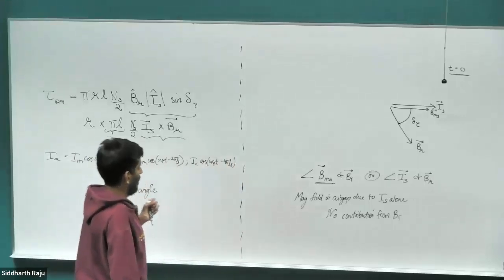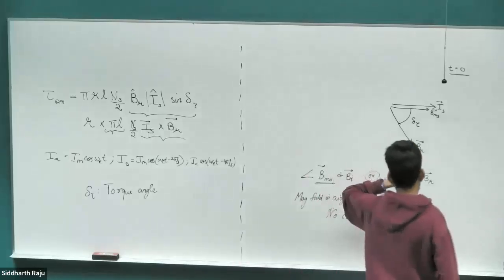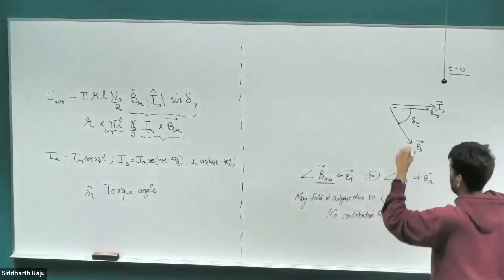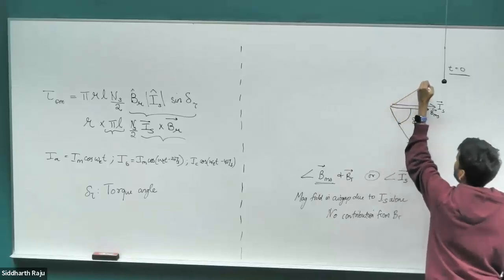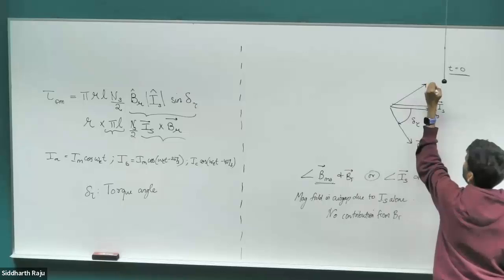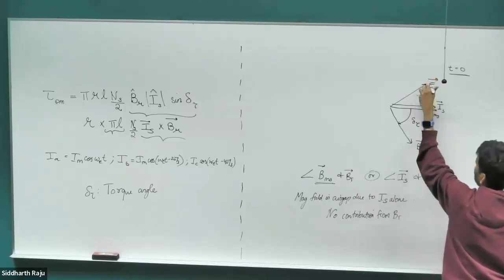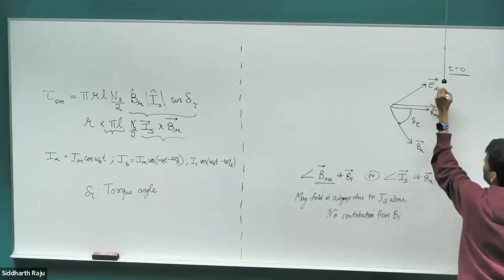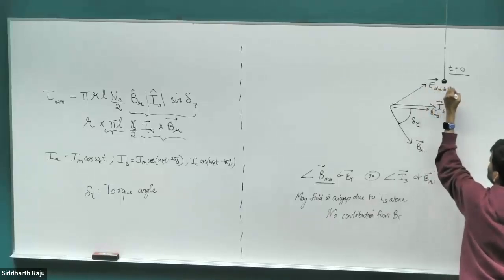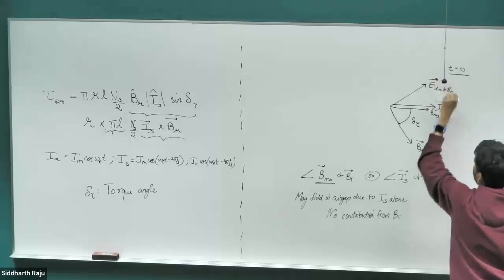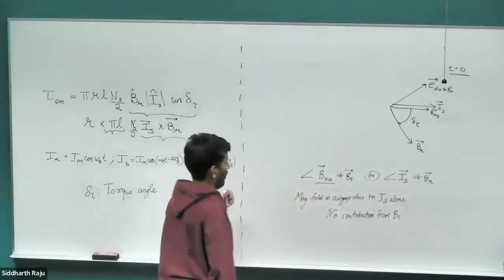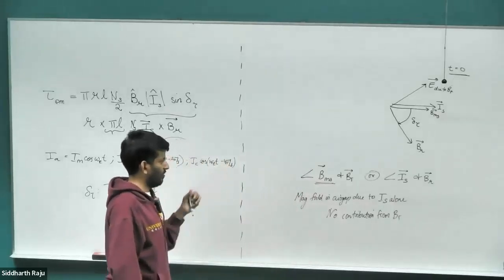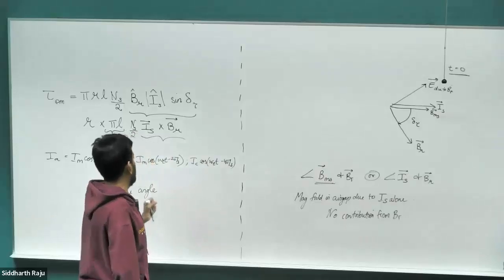Okay. So we have this. This is what we had before, and then we had our EMF space vector, which was 90 degrees ahead of the BR space vector. So this was our stator EMF space vector. Let me put a subscript to this, EMF due to BR. So this is the EMF induced on the stator coils due to the varying magnetic field of the rotor as the rotor starts to rotate. So this is what we have.